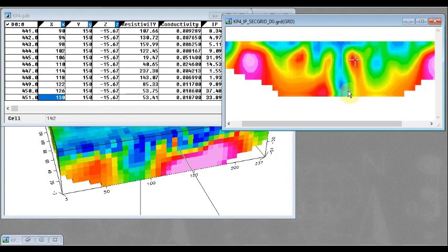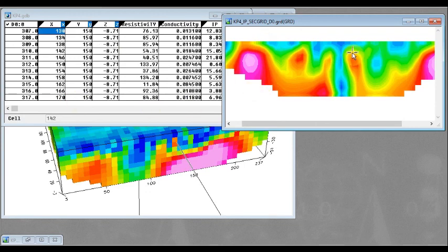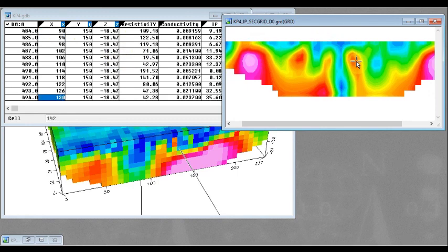And you can see a very clear demarcation that there is with index. It showed up there. You might not have to, but if you look at it, you can see a very clear demarcation here that something, there's a fracture here. You get it now? If you want to look at more information at this particular depth, you can see the top of the anomaly. Look at the Z. It's minus 8. The center is about minus 18.4.